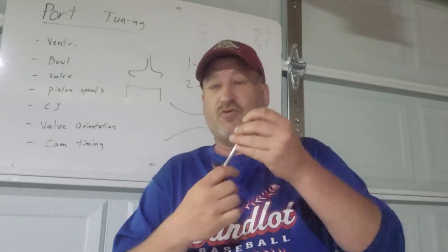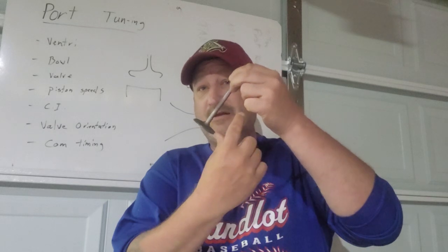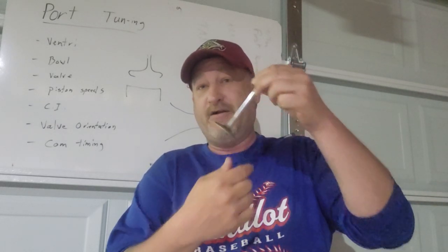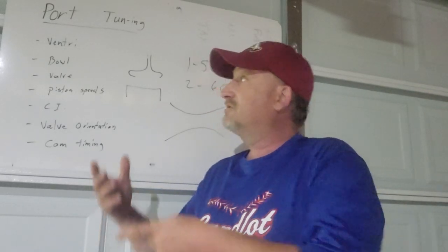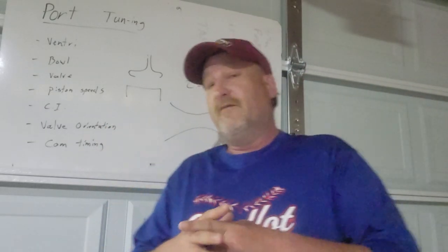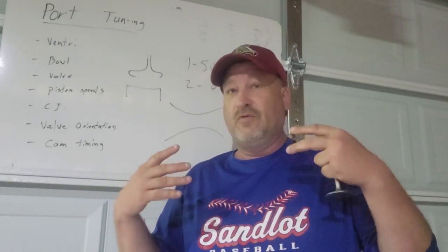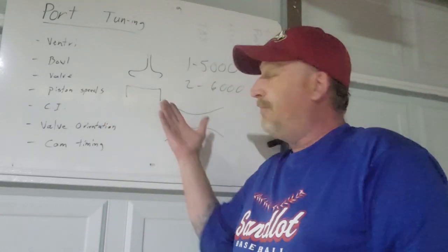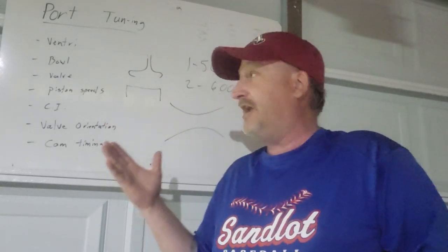As RPMs increase, it's much more important to open that area between the seat and the valve. The curtain area, again, is going to be very important. It allows more of the vacuum to be exposed to the port. So all of those parameters need to be overlapping. All of the parts have to work together to allow each component to function within its intended performance range.